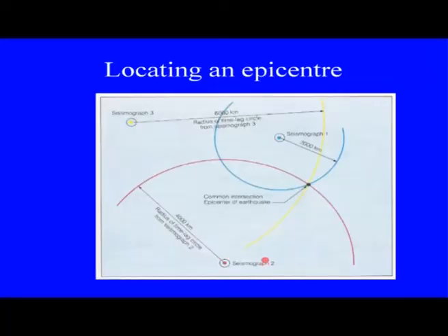As I have told you, the earthquake occurred at a particular point. There is one seismograph here, another seismograph here, another seismograph here. With one seismograph, you will get one time, and on that basis you make one circle. That means it is anywhere within the circumference of the circle. Wherever the circles meet, at 2 points they meet, that means either it can be here or it can be here. Now when you have a third seismograph, then obviously I can say this earthquake is somewhere here. So that means a single point, and I can find out the location of the epicenter.